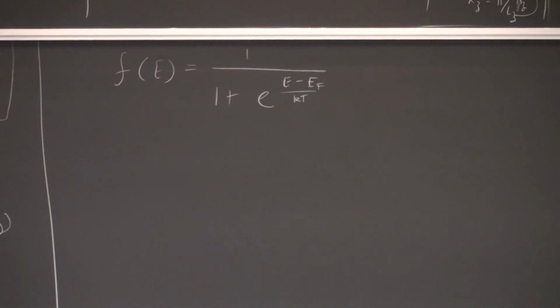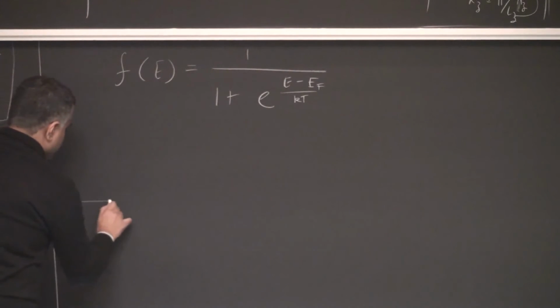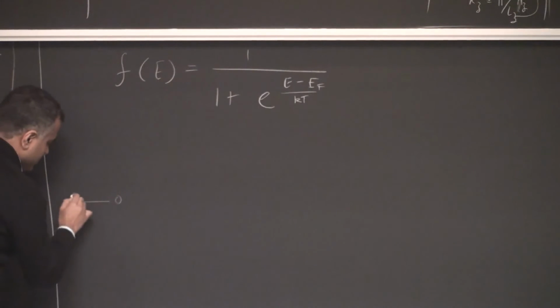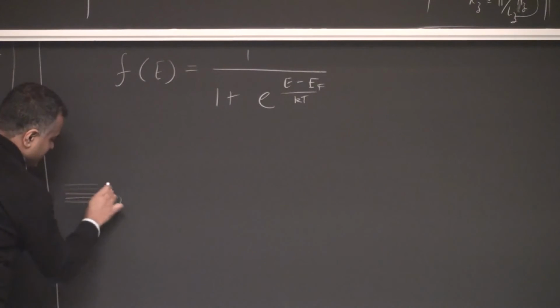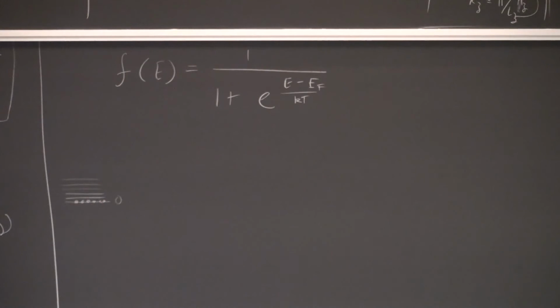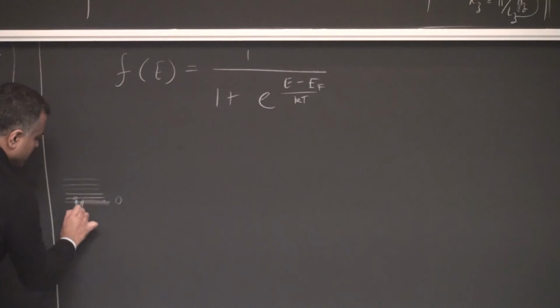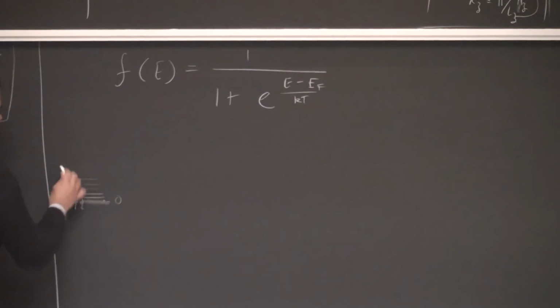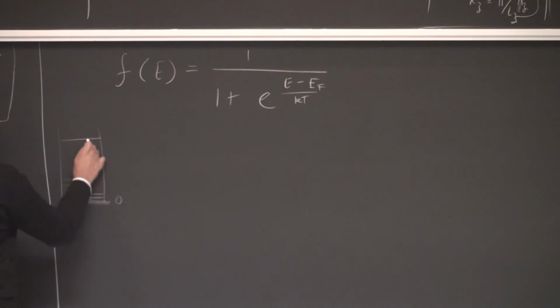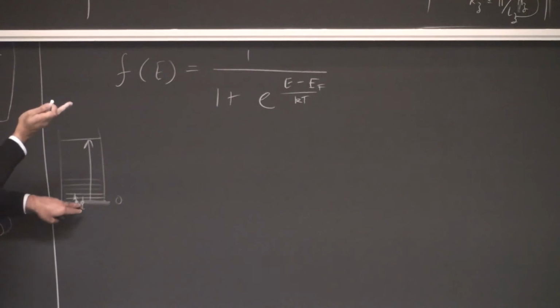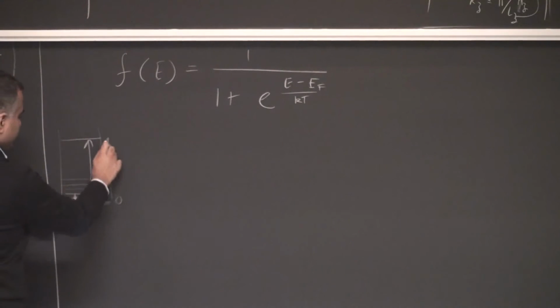Unlike photons, if I have, let's say, some zero of energy, and I start pouring electrons in, one of the very important things about electrons is that not all of them want to stay at the bottom. There's an exclusion principle, which is why I can only fit 2 electrons, one up and one down here, one up and one down here. Therefore, when I fill a bucket of states with a lot of electrons, you immediately fill the states up, and the maximum energy rises very fast because they're not allowed to have more than 2 here. And this measure is the Fermi energy here.